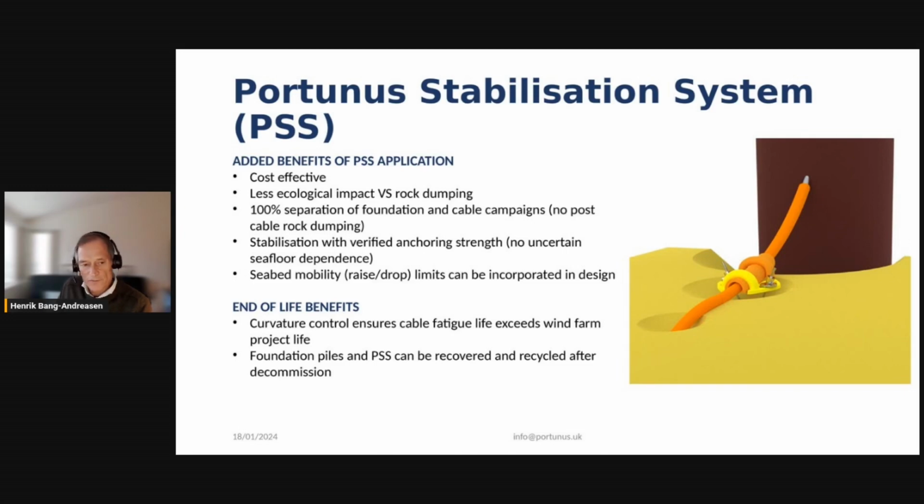And of course, the end-of-life benefit is, first of all, that the curvature control ensures that the cable fatigue, and similarly the CPS fatigue life, exceeds the wind farm project life, and that the foundation piles and PSS can be fully recovered and then also recycled and decommissioned. So after decommissioning, there's nothing left at the seabed. Everything is fully recovered and removed and can be recycled onshore.